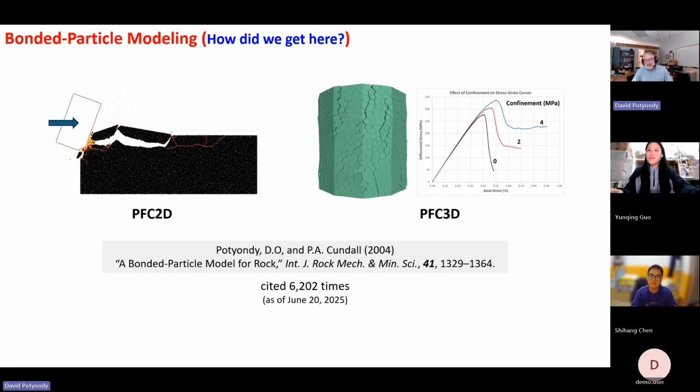But then if you take the same rock and you put a sleeve of rubber and you apply fluid pressure to the outside, you can maintain that fluid pressure constant during the test, and you will get a higher value at which it begins to fail. So this is 2 MPa confinement. This is 4 MPa confinement. Okay. And also, if there's no confinement, it fails, it drops all the way to 0. Right? It just disintegrates.